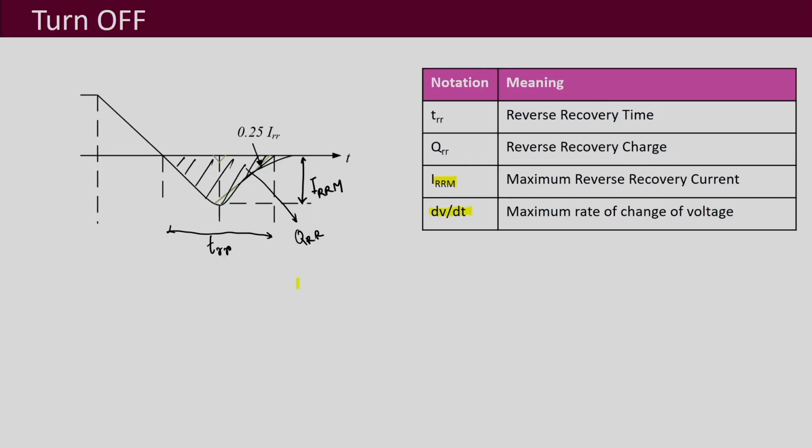Many of the data sheets do not provide it, and the reason for it, that we have seen before, is that the T on time of the diode is smaller than the T off time. So, the switching frequency of the diode, Fs, is limited by T off, and that is why it is usually the T off times and the reverse recovery time that are provided. This QRR and IRRM are more of a concern in many applications of fast recovery diodes.